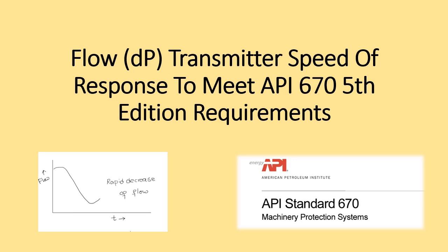API 670 is the standard for machinery protection systems, and in its fifth edition, it provides specific guidelines about flow transmitter speed of response for the anti-surge detection system. In this particular lecture, we are going to discuss the specific criteria of the DP transmitter used in the anti-surge detection system.